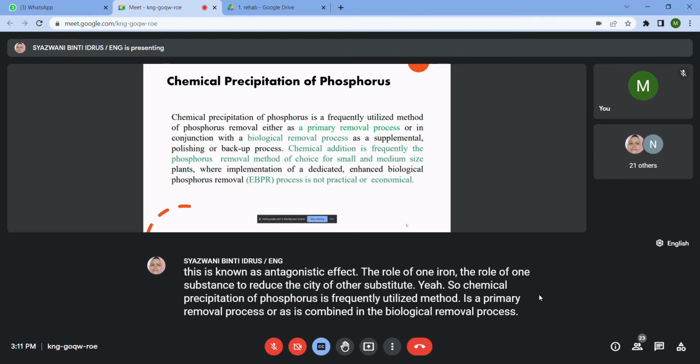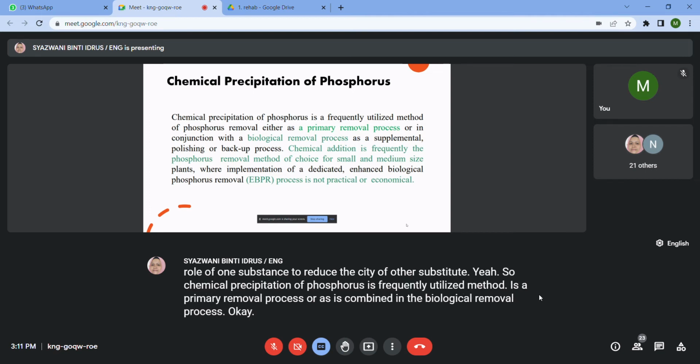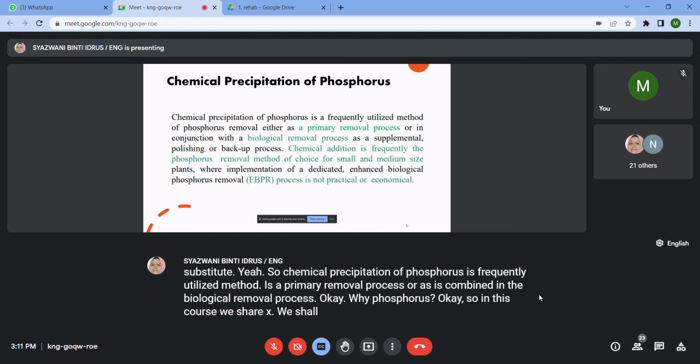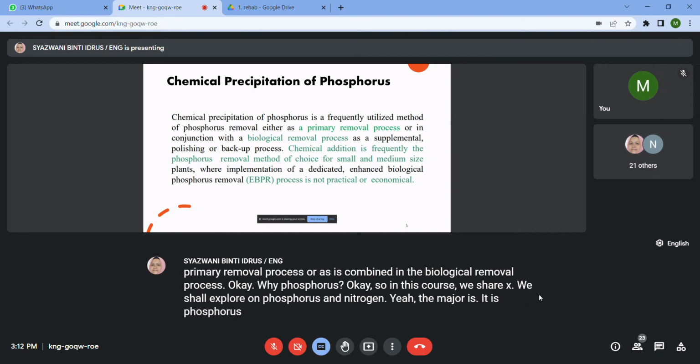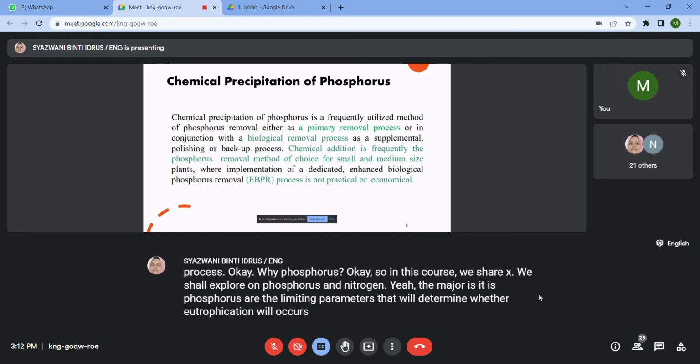Why phosphorus? In this course we shall explore phosphorus and nitrogen. The major reason is that phosphorus is the limiting parameter that will determine whether eutrophication will occur or not. I repeat, why phosphorus?